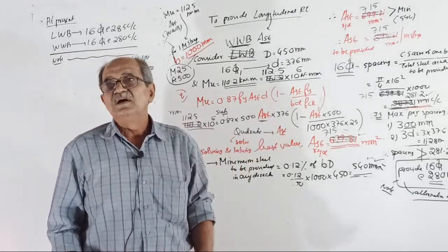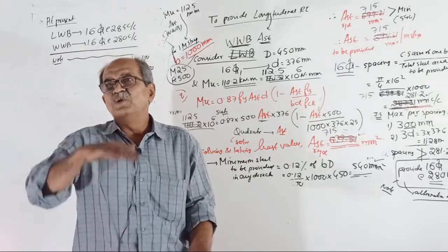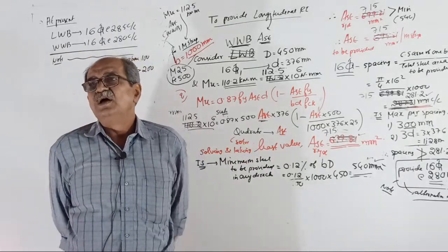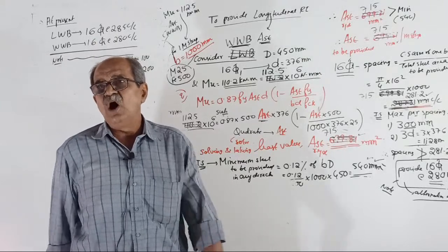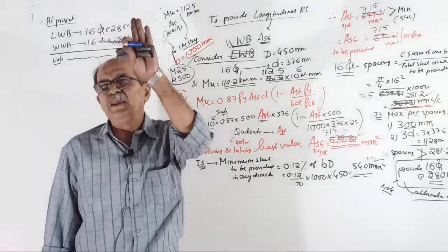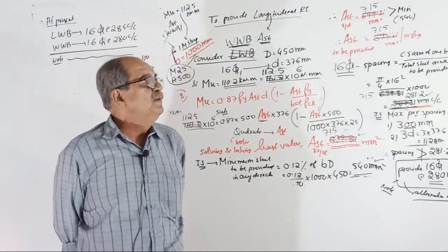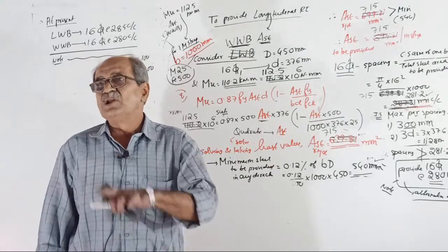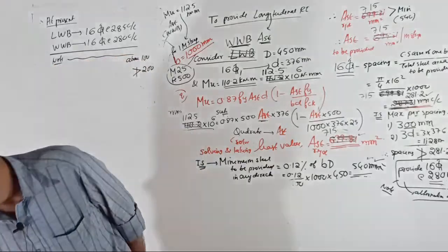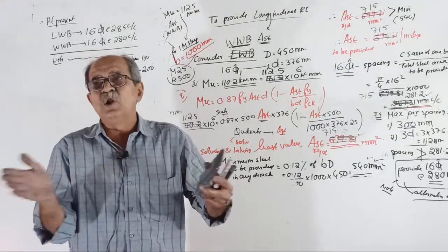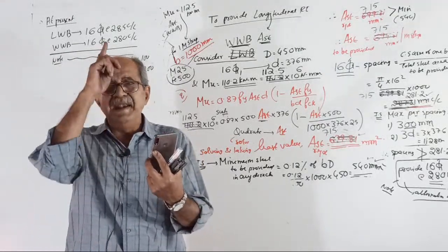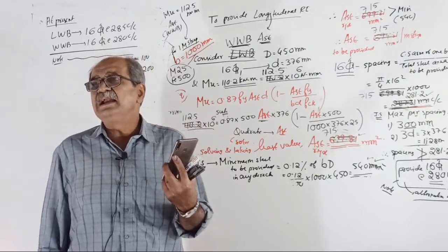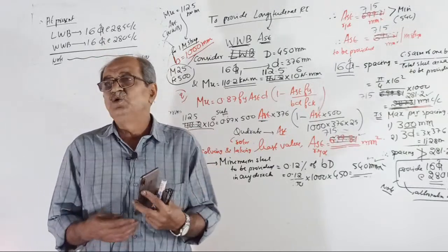Also, I told earlier, when you decrease the diameter, your D will increase. So, is it on the safer side or unsafer side? I told you repeatedly in earlier classes. If you take a diameter and later the diameter is decreased, is it on the safer side or unsafer side? Because why? Spacing is closer. I told repeatedly earlier, decreasing the diameter results in slightly higher D. It is going to be on the safer side.